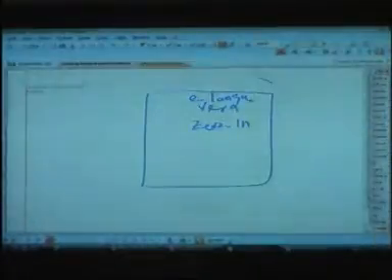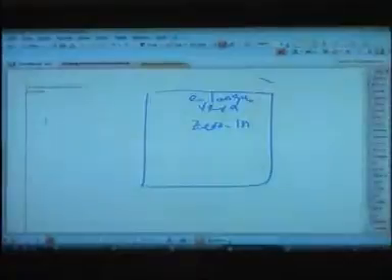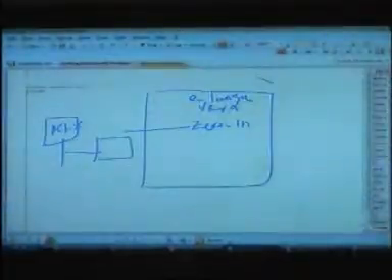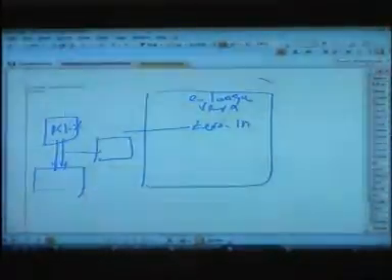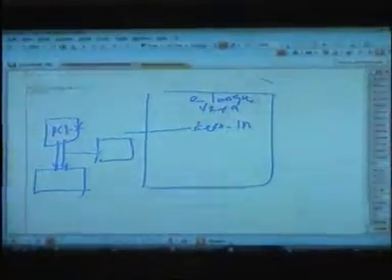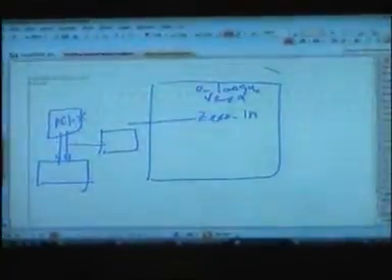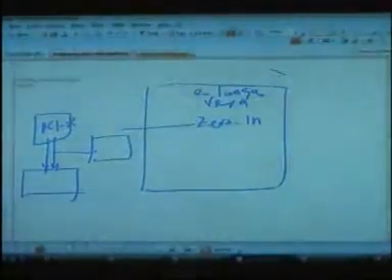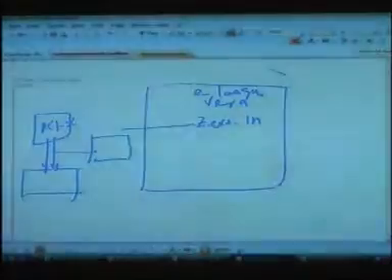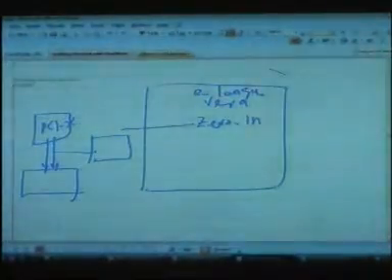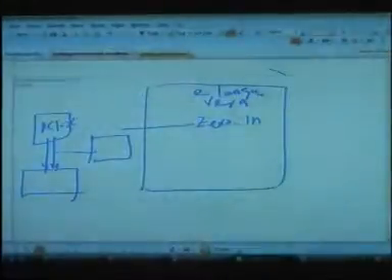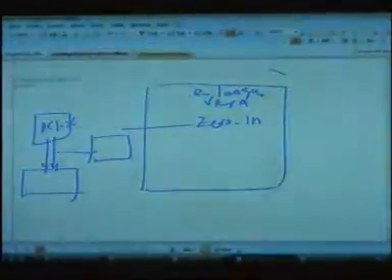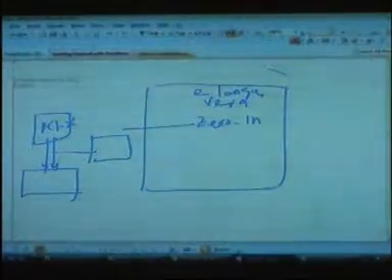I'll give you an example. You are designing a PCI interface, a PCI-X interface. PCI is a standard interface. Now you need to go to Zero-In and ask them to give you a checker. A checker checks all the signals you are actually using at your interface. So whatever transaction your design is making, the checker will test whether those are legal PCI transactions or not. If they are not, it'll complain, saying you cannot do this. After a request, so many cycles, you need to get a grant, or things like that. So they sell these checkers, and checkers are for the standard protocols.